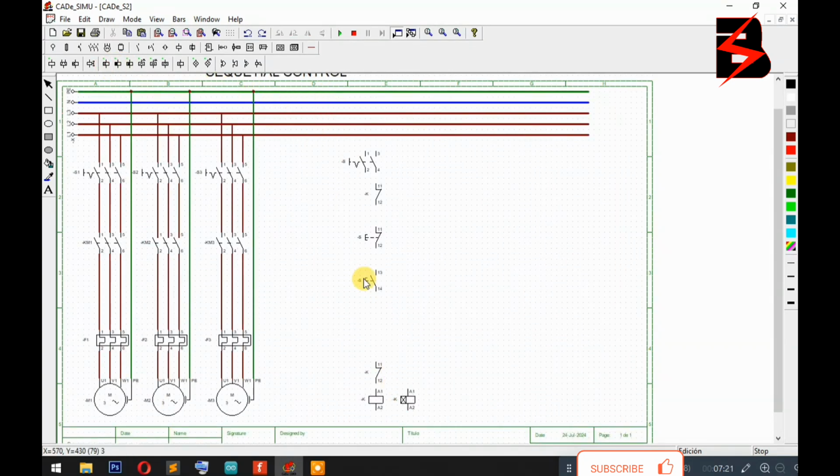So when we do the cabling a bit, let me use this one as my control. I'll get from the nearest phase to act as a live, then through the overloads, then through the stop. This one is not the stop, that one is emergency. Then start.